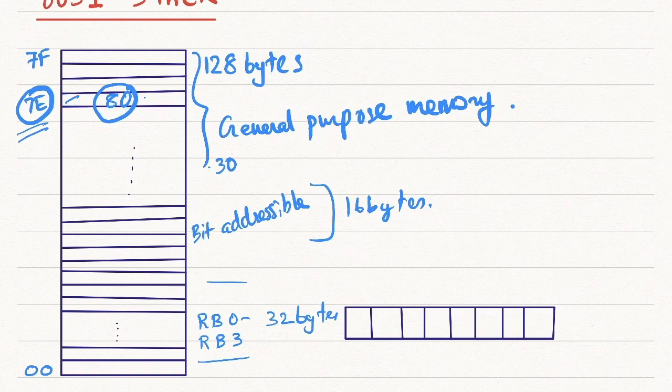So the stack is used for storing this data temporarily using some instructions. Coming back to the definition, we said this information could be data or an address. When I say address, when you use subroutine programs, the concept of pushing the address using the call or return instructions is very important, because subroutine programs change the program flow from one particular location to a totally different location.